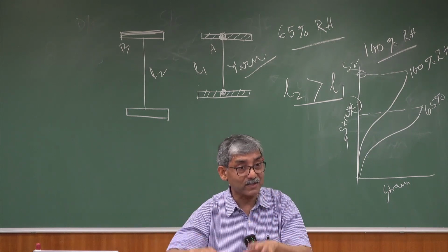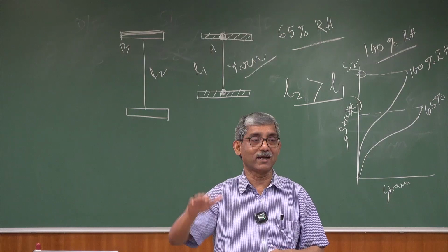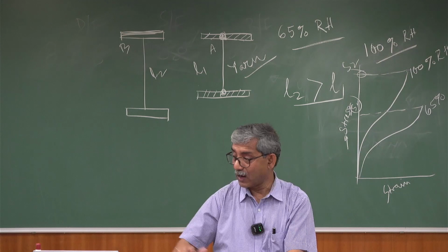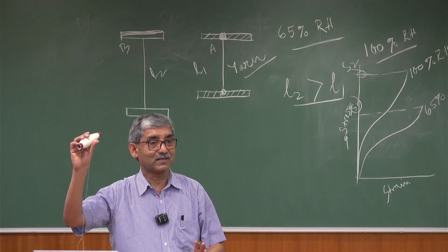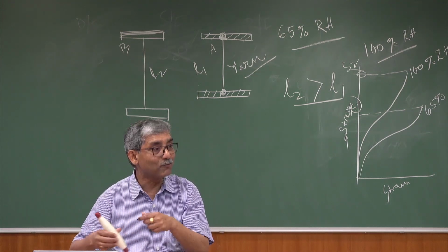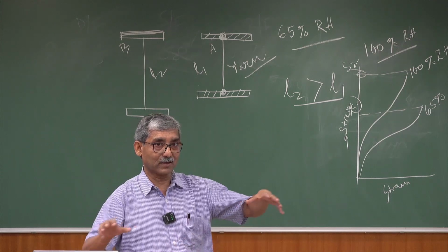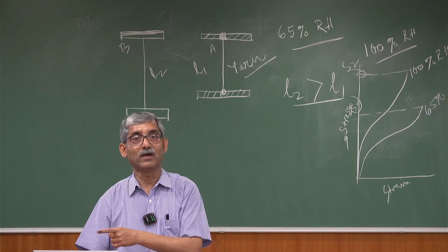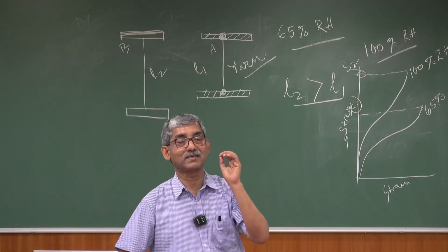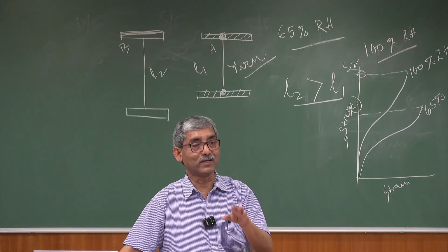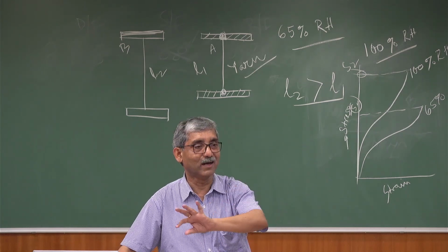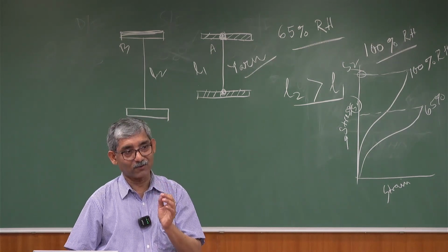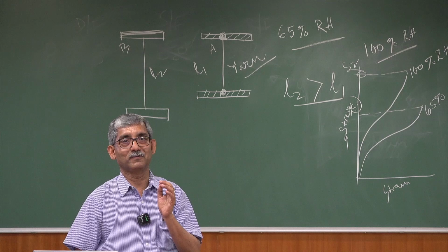What is the CV percent or variability in linear density? That we are testing here to achieve a certain standard uniform quality. So it is the application of statistical techniques for quality control, like mean, median, mode, or maybe significance tests. So that is actually statistical quality control.